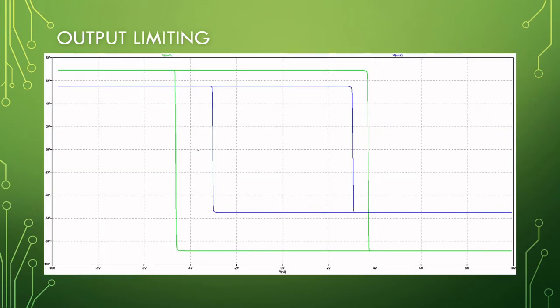Okay, in terms of symmetrical and non-symmetrical, adding two similar diodes will yield this blue one over here, symmetrical trigger points, symmetrical limits. Having two different diodes, look at the difference between the triggers. They are not symmetrical at all. So trigger close to 4 volts, trigger closer to 4.5 volts. And a limit here at about 7 and a limit here at about 9 volts.